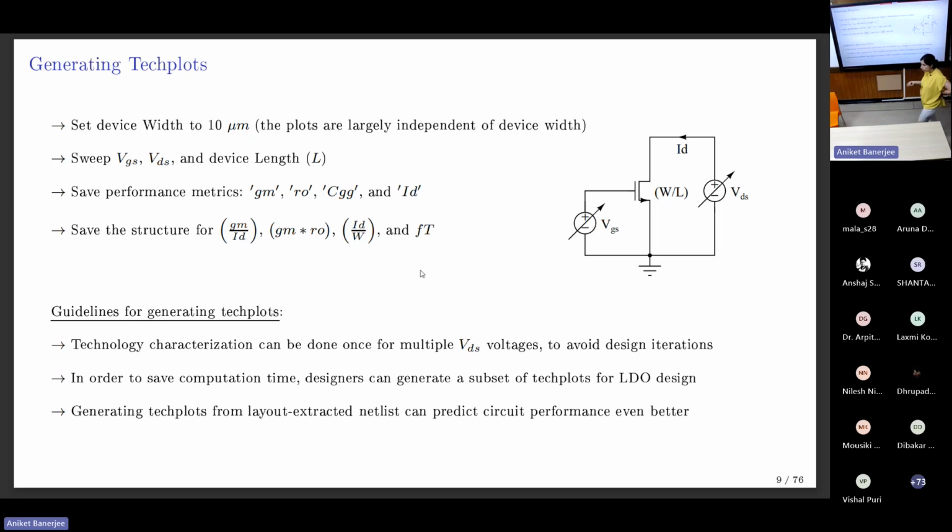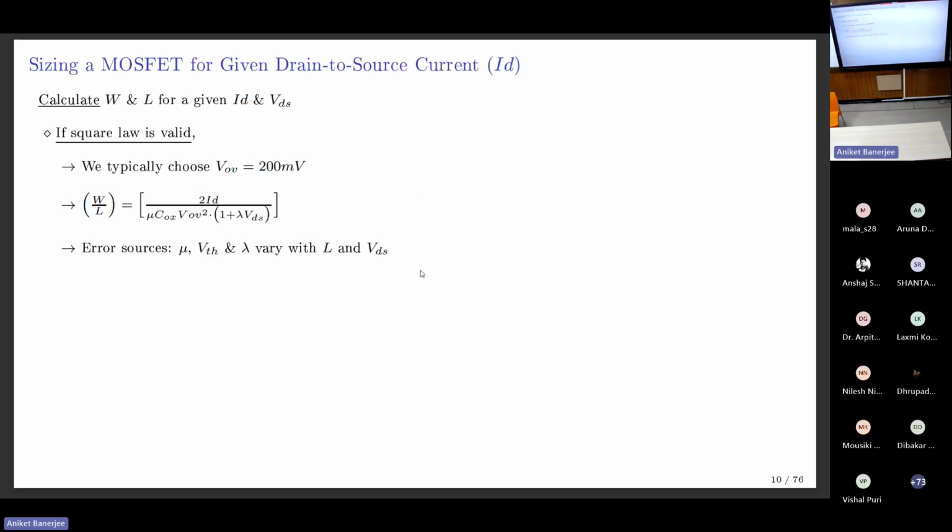This will be so powerful to let you design a FET with confidence, and we call it first-time-right design. So if you do this well, you are saving yourself a lot of SPICE iterations, right? So you generate this. And using this, now I'm going to share with you how to design the FET, conventional versus gm/ID. Now we are together slowly to design the LDO together. But this is the first step, this is the FET.